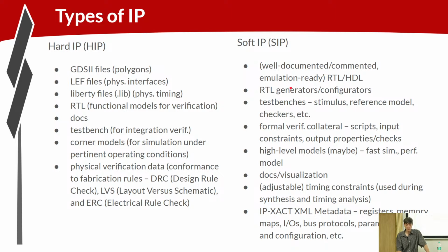You might also be delivering generators of the RTL. Your customer might want a certain configuration of your design. TL-Verilog is helping with that, right? TL-Verilog itself has mechanisms for configurability that could be valuable in this context, but generally RTL itself is not very configurable, so often folks delivering IP will develop their own tools to help customers configure the RTL to their needs.